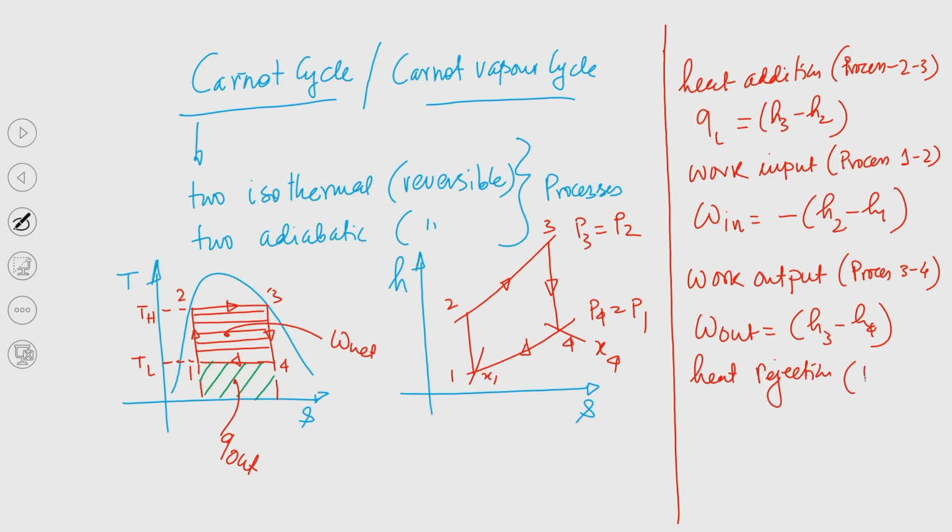That is process 4 to 1, this is Q L, that is minus H 4 minus H 1. So, again this is rejected. So, I am writing following the convention of the first law of thermodynamics, I have written this negative sign. I am not going to, so I have straightway written this equation. Perhaps Professor Sahu has discussed about the basic laws to describe these, I mean that those will be required very much to understand the subject, the content of the subject.